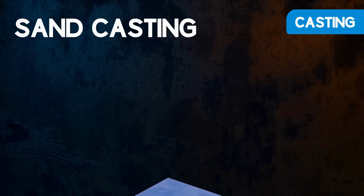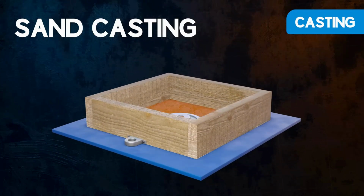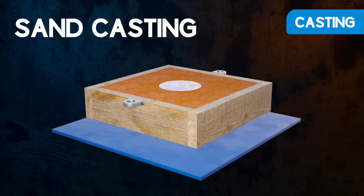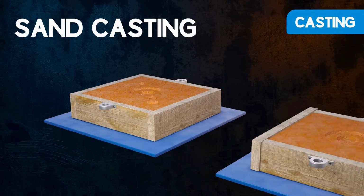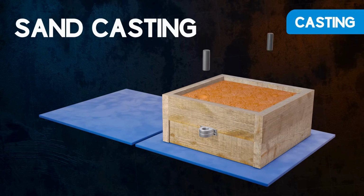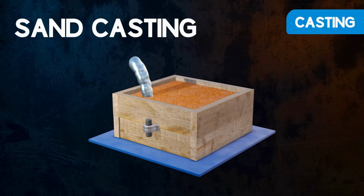In sand casting, a pattern is used to create a single-use mold from damp sand. The sand is typically contained in 2 mold boxes, called the cope and the drag. Molten metal is poured into the mold through a channel formed in the sand.